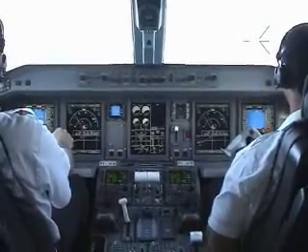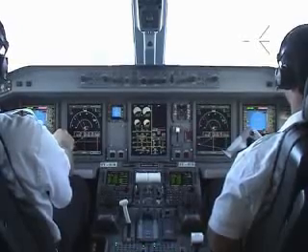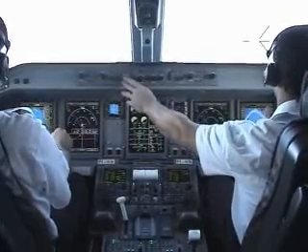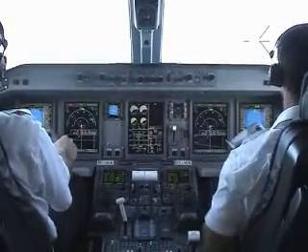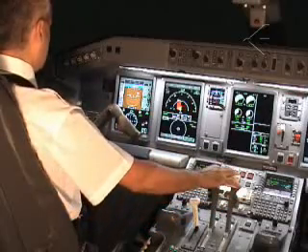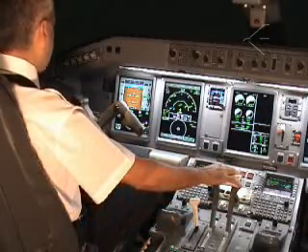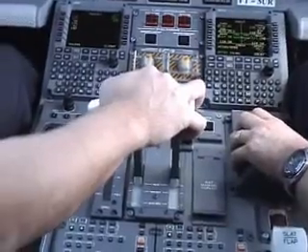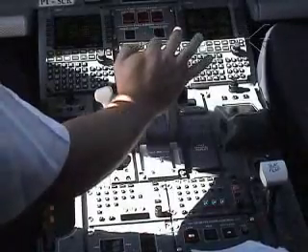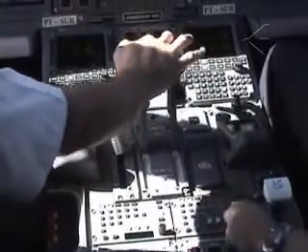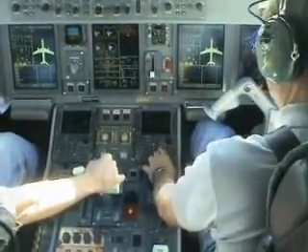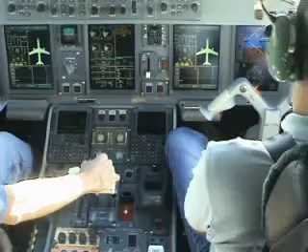During the approach, the pilot flying's primary tasks are supervising and decision-making, while the pilot not flying is monitoring the operation. Pilot flying will be head-up, guarding controls, and continuously ready to take over. He or she will take the appropriate decision in case of failure and at decision height. The pilot not flying will be head down and monitors FMA, any failure, and aircraft trajectory.